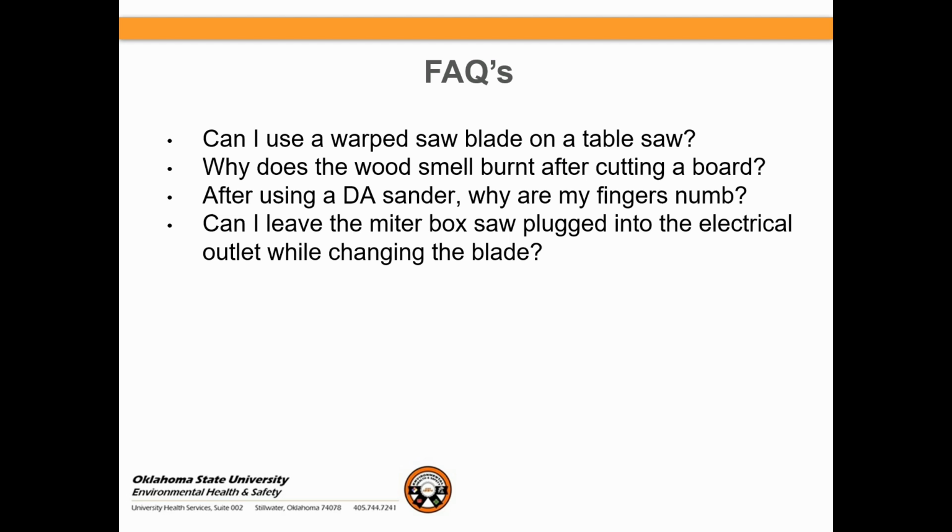Can you leave the miter box plugged in while changing the blade? The answer is no. We don't want any sudden, unexpected startups, is what we're trying to avoid.